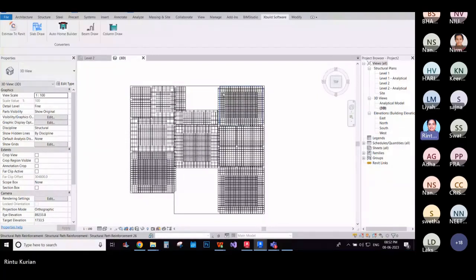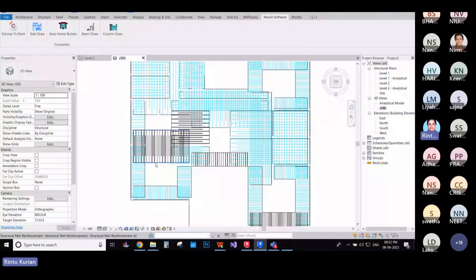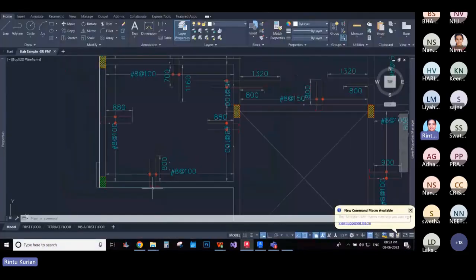All arranged, alternate bars are correctly arranged. We have the same shape bars arranged. The only thing is that this is not the one with bend lengths. So wherever there is a bend length, just select the bar. We'll just go and check here. AutoCAD file, we have bent bar here and bend length is nearly 100.